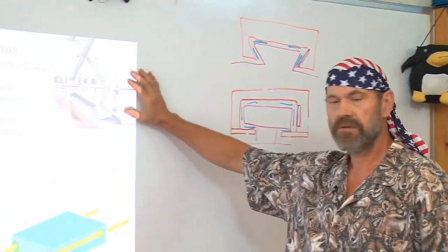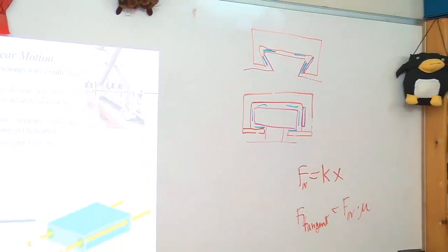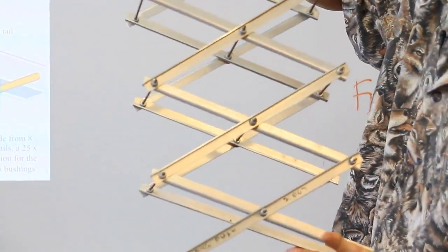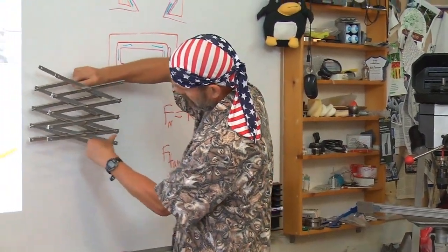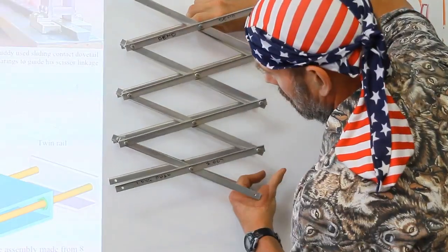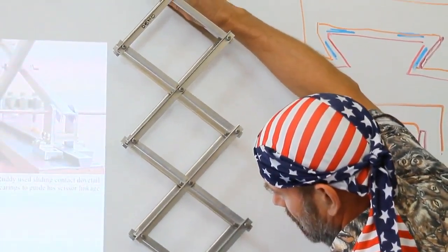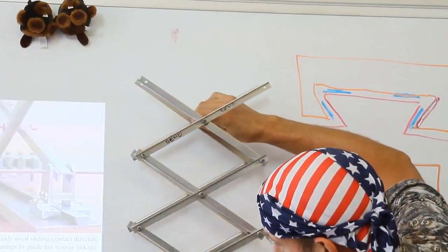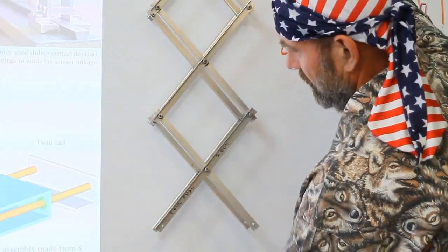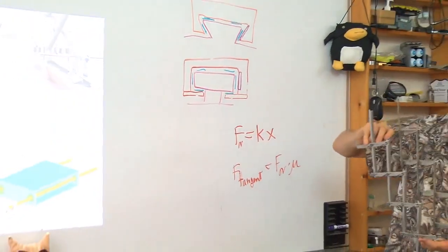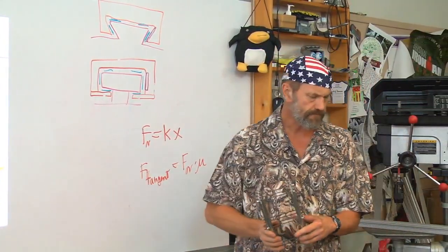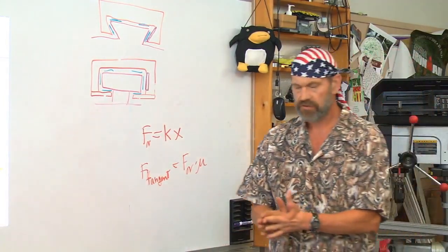When you look at construction sites, you'll often see the scissor lifts going up and down. Notice how if I pin this joint here, there's going to be a gap opening up. See how that gap opens up? You have to allow a linear motion bearing with that scissor lift. So you have pivots, and you'll still have to have a linear motion bearing to allow it to slide in. What kind of linear motion bearings do they use on scissor lifts that you'll see, for example, at construction sites? How do you design a bearing to last in a construction site?